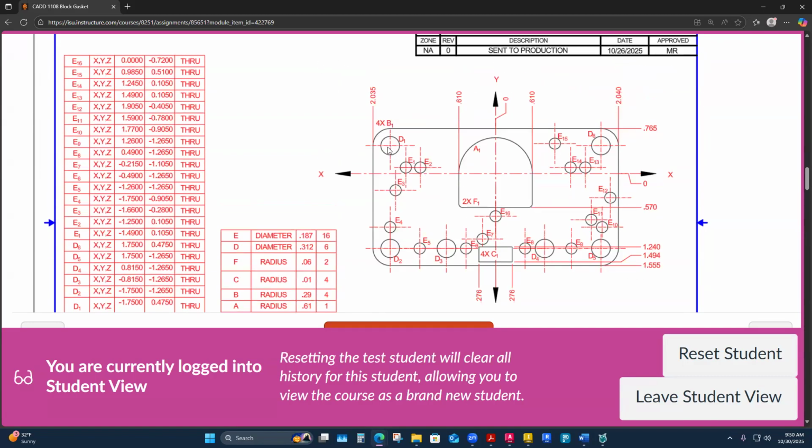When I finished my drawing, I didn't show that, because maybe it would cause more confusion than not. But what's maybe a little misleading here is I probably should tuck these center lines away. I think I tucked this one in because it was conflicting with my radius callout, so I strategically tucked it in so it doesn't hit my text.